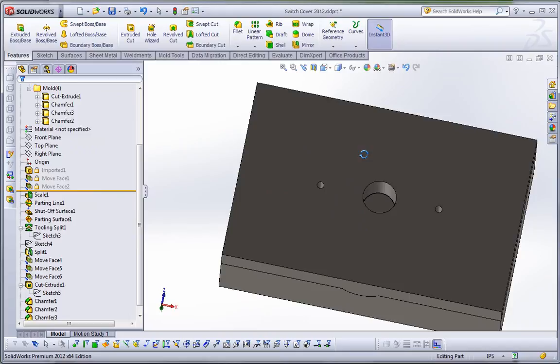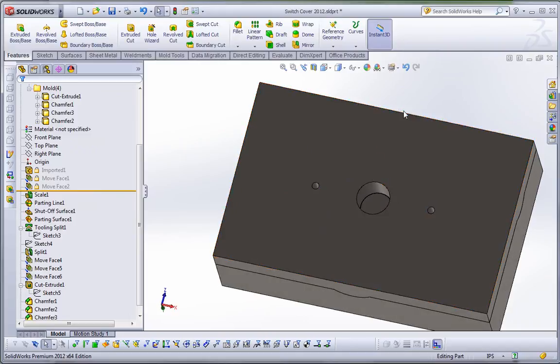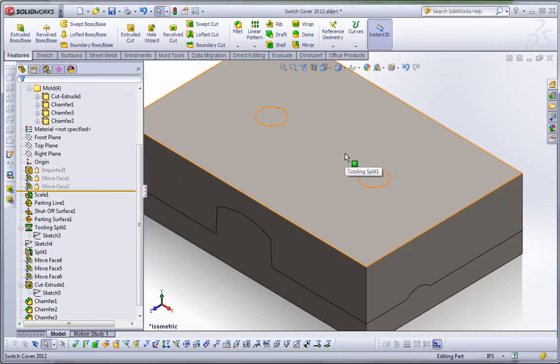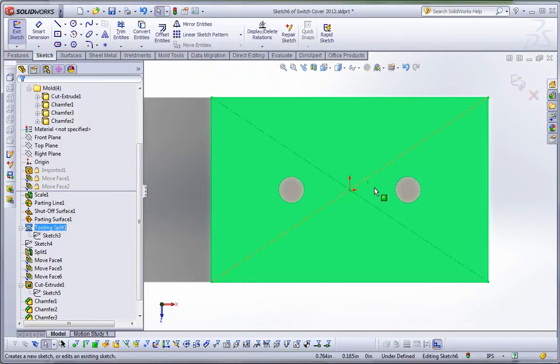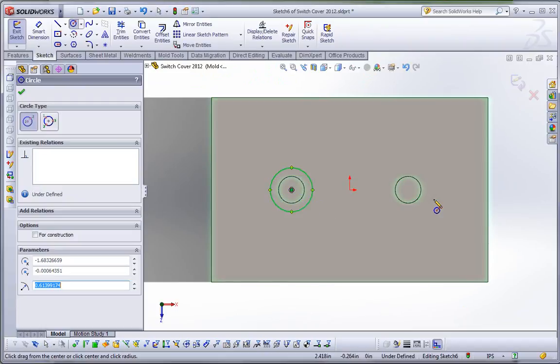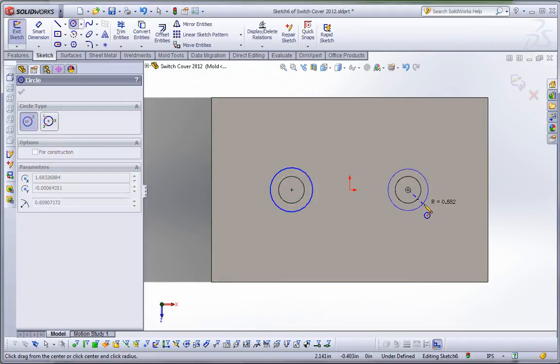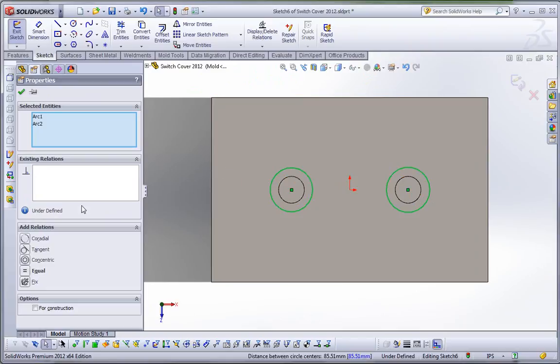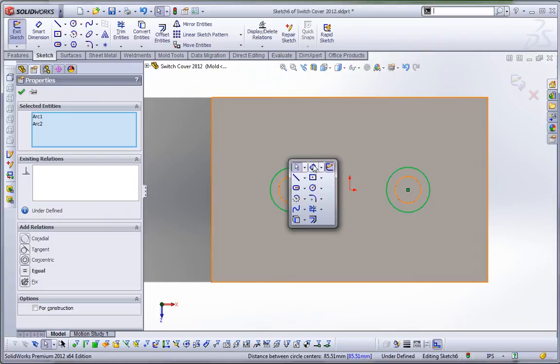So now as it relates to using Direct Edit again, I'm going to go ahead and create some pockets or some heels for those pins. So again, I'm going to come back in, create a sketch. And you'll notice that what I'm doing is purposefully implementing symmetry in the sketches and then using move face to move the faces in versus spelling out the dimensions directly.